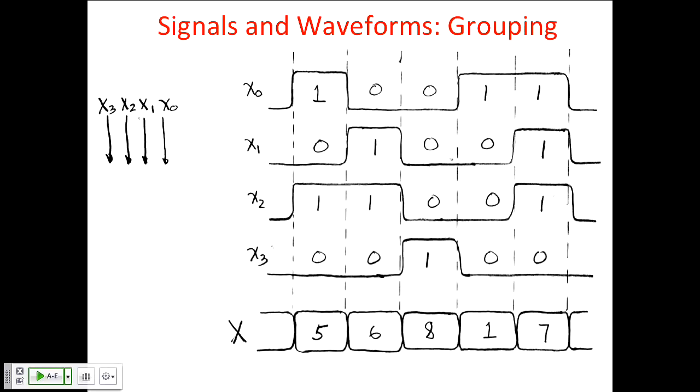Just want to go back again to some notation. When we draw one line like this, it's pretty easy to see it's a 0 or a 1. And we can just draw it as, at the bottom of the trace, it's a 0, the top of the trace, it's a 1. When you have a multi-bit signal like this, you draw the convention like this. We kind of have both the 0 and the 1 line drawn together, like you have a 0 line, a 1 line here. They're both filled in. This represents the fact that across these bits I have multiple values that can be either 0 or 1. And notice I just draw this kind of crossover where they change, right?